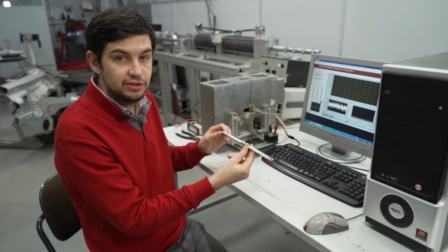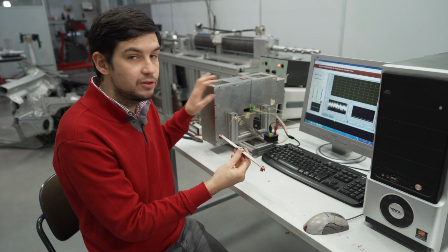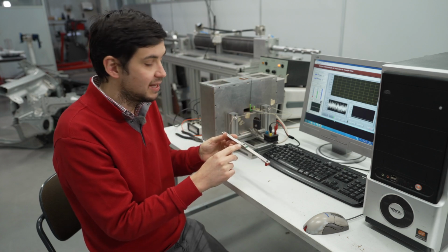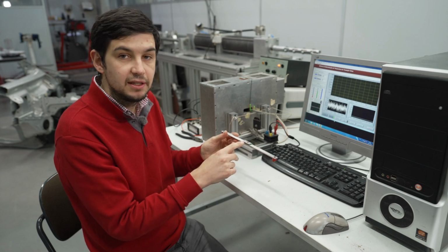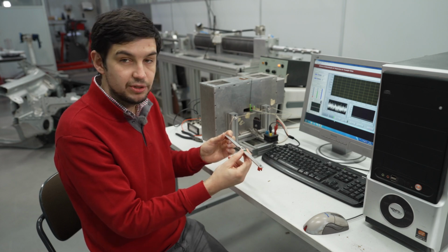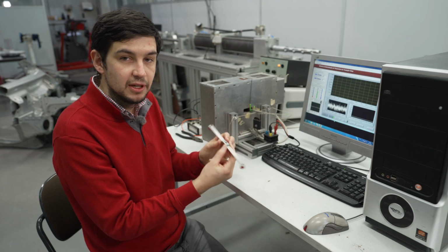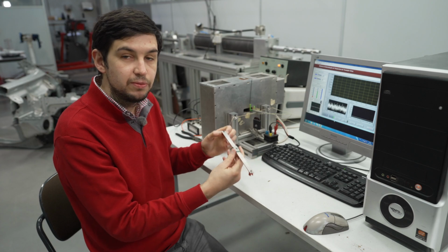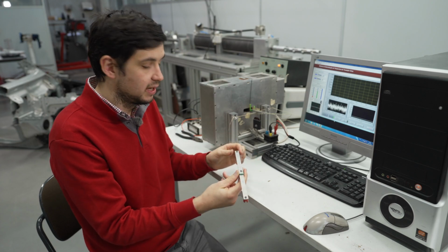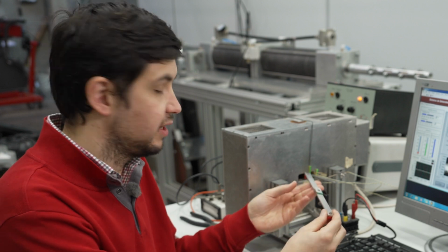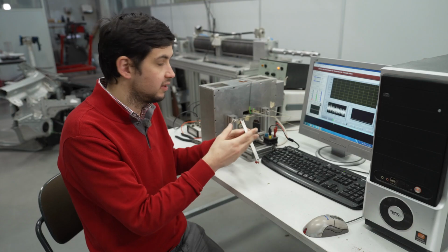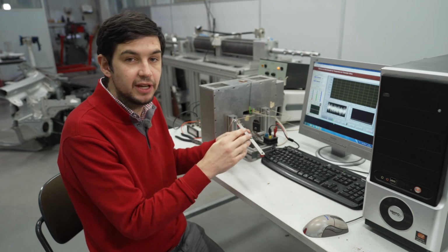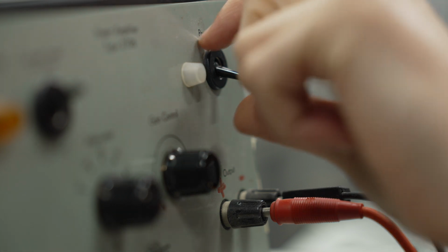To determine the glass transition temperature, what we need to do is use this oven to increase the temperature gradually until we reach a point where the specimen damping is maximum. This means that the adhesive has reached the glass transition temperature, and during this transition it becomes very capable of absorbing these vibrational movements, and this will be reflected into a peak of damping. So we will insert the specimen within our testing machine, and we will start the software that will put the specimen in resonance, increase the temperature of the oven, and then detect the glass transition temperature.